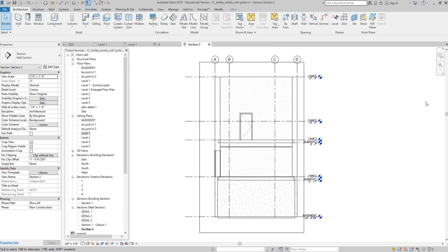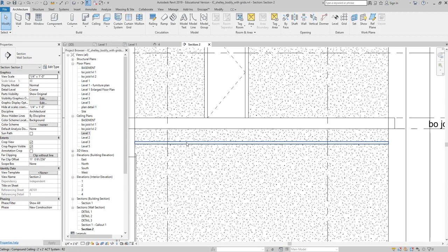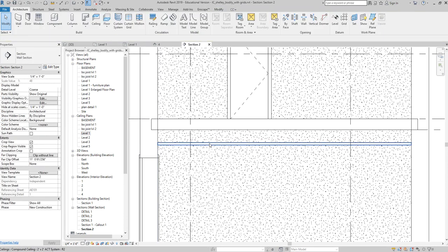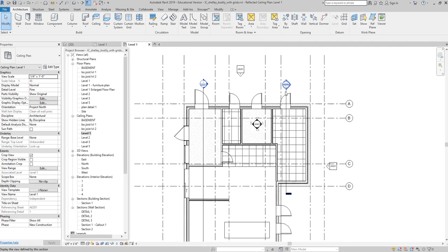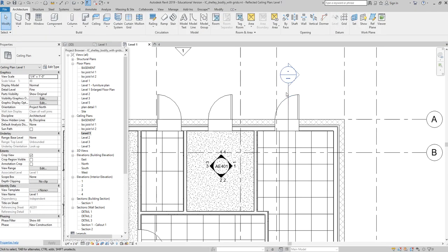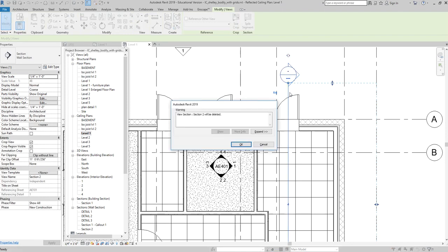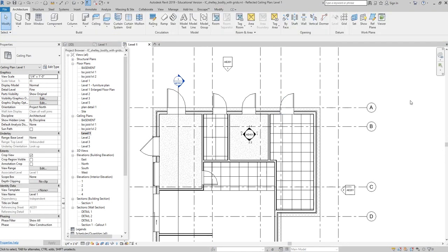So click on that section, and maybe I was just drawing that section to see where my ceiling was, and AL align, click. That's where my ceiling needs to go, right? I needed that section to align it. And then I click on that section, whoop, delete, okay, and it's gone, right? So you can pull these views, you can delete them when you don't need them anymore, but they're very helpful to help you generate geometry, okay?